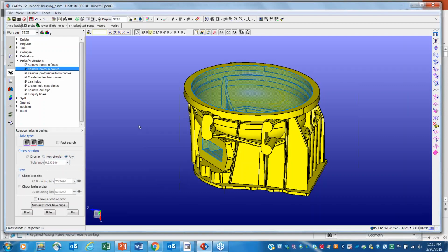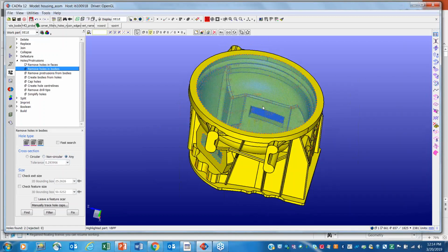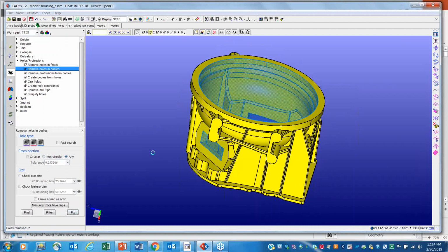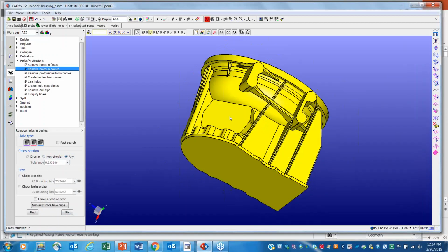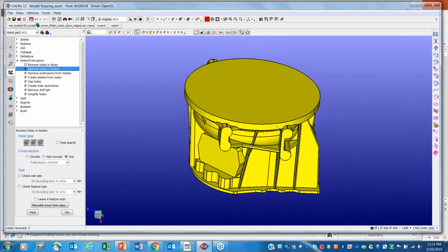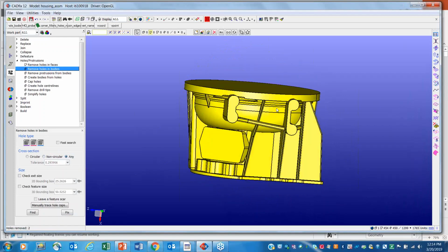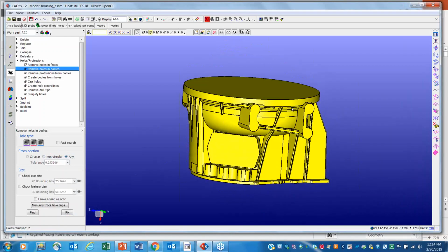And it's going to come back and you can see that it finds this one hole that's a rectangular hole on the side here, and then it finds the entire hole that basically is the whole interior cavity of this part. And by doing this, I'm really simplifying the model, taking some IP simplification here, and filling in this whole thing to be solid. So we don't have any interior to this casing anymore at all.